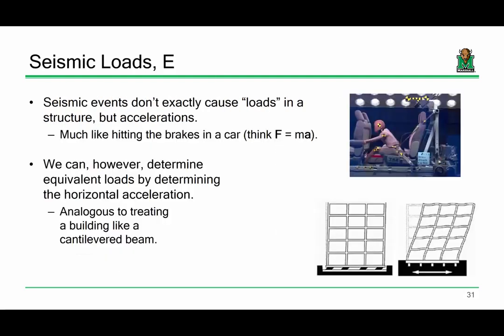And so we started talking a little bit last time about seismic, about earthquakes. Where you get your earthquake loads, the forces that you apply for structural analysis, comes from F equals ma, force equals mass times acceleration. The building obviously has a mass to it. It's not light as a feather. It has some significant weight.